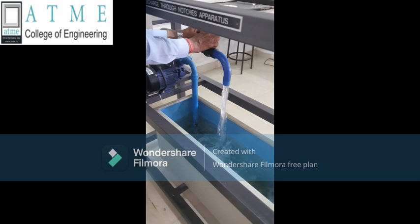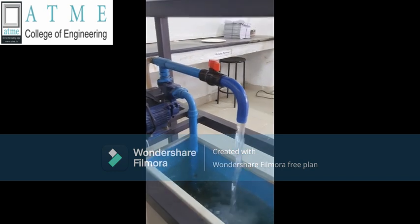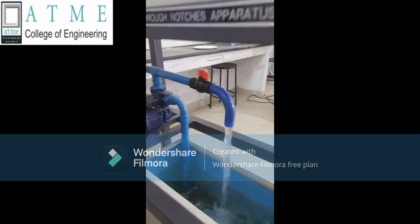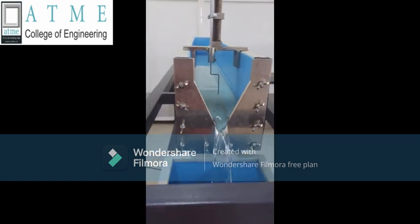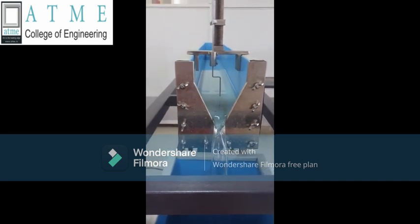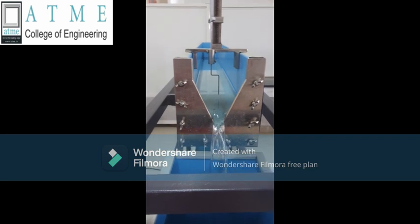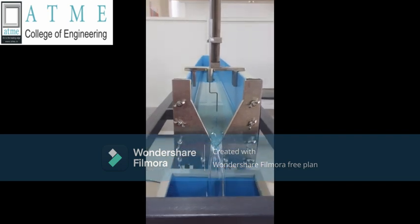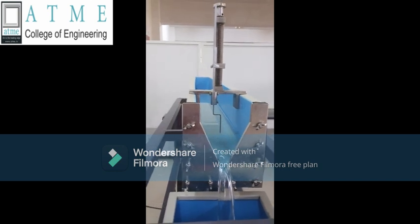For the third condition or the third trial, open the flow regulator valve completely so that the discharge level will be reduced in a channel. Again, after some time, when the flow becomes steady, adjust the point gauge and note down the reading as H3.